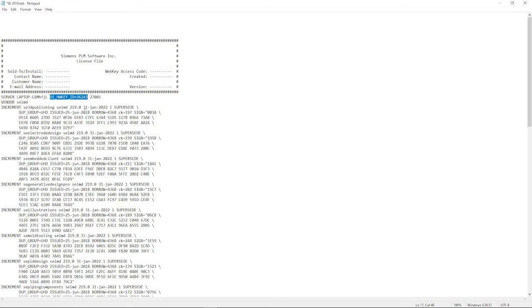But they made it so that the VM could recognize a USB port on the physical machine that was hosting the VM. But in most cases, you cannot get a dongle-based license to work with the VM. But if customers don't tell the VAR that, or the VAR doesn't ask that, if they forget about it or don't think about it at the time, the license file you are by default going to get is this hardware key ID based license, and it won't work with your VM. So you have to get a unique host ID method.